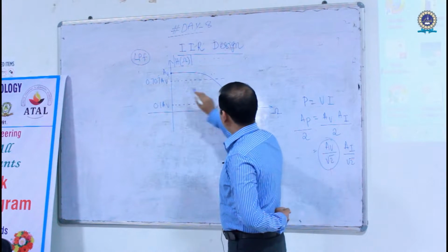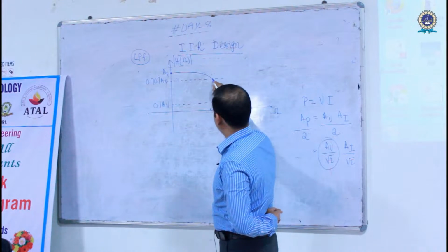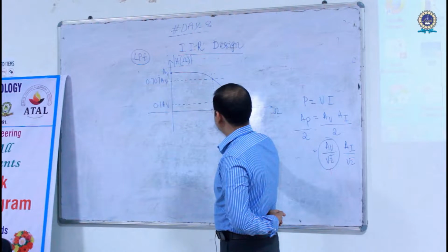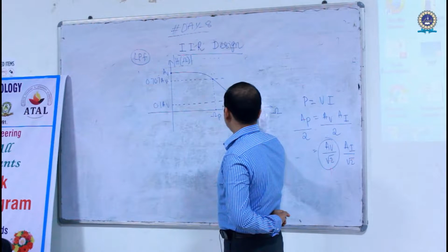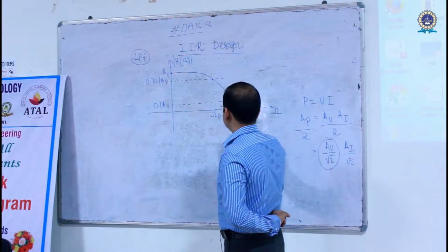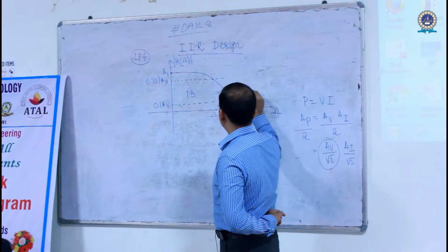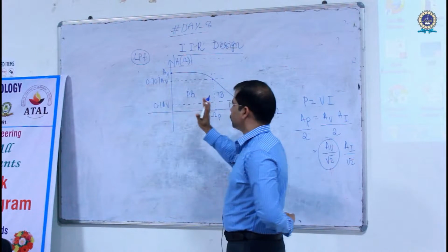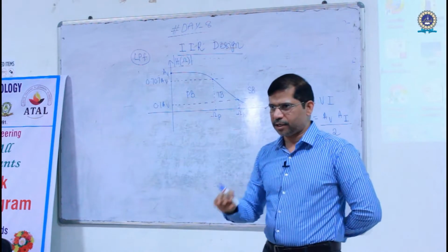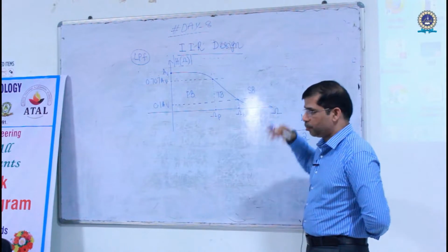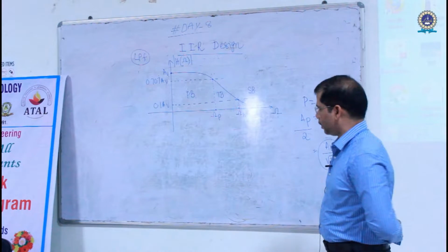So this particular one will cut the magnitude response at some point, and you have to drop it down. This is what you call the passband frequency, and this is what you call the stop band frequency. Now this is my passband, this is the transition band, and this is the stop band. So this is the ideal way of drawing the low pass filter characteristics, but not exactly, because I'm going to draw one more graph now. That's where you can expect the more practical things, right?